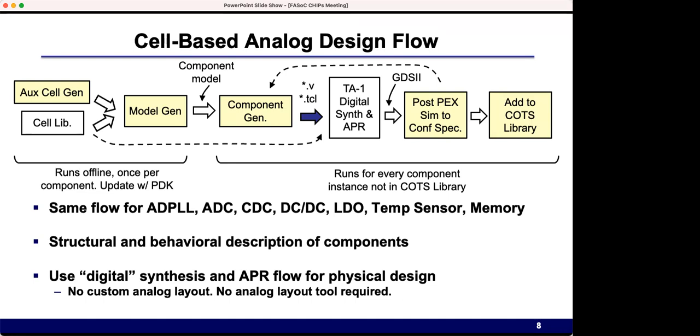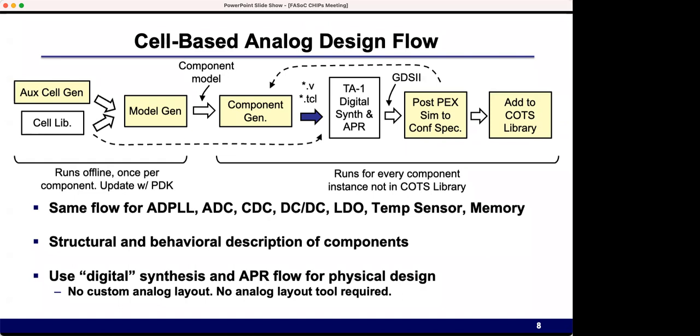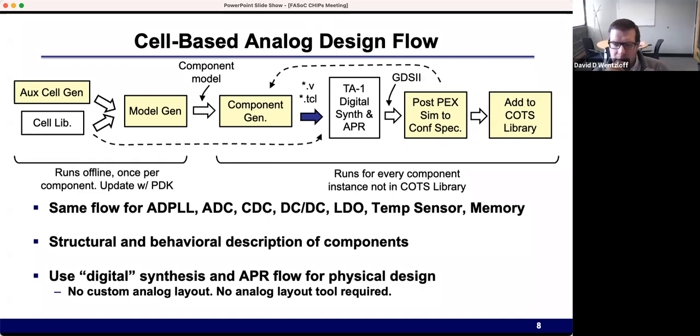Right. Another approach that we had looked at back in my industrial days was a mixed-mode capability for our gate analysis tool, so that depending upon the design, in particular the clock grid, we were able to dive down into the SPICE-level representation and simulate it, and then annotate that dynamically back into the gate level, but that's a further out topic. Just for the clock grid? The clock grid was done at SPICE level, but the remainder of the design was done at gate level, using Liberty abstracts. Yeah, interesting.